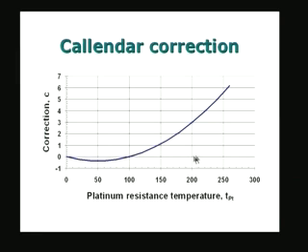And as you go to higher and higher temperatures, I have shown up to about 250 here, the temperature correction could be as big as 6 degrees. What is the advantage of this method of calculation? So, what I will be doing is, I will be calculating T PT using the linear relationship and then calculate the corresponding value of the correction using the linear temperature which has been calculated and putting it into the equation for C, and then I will be able to calculate the temperature without much difficulty.